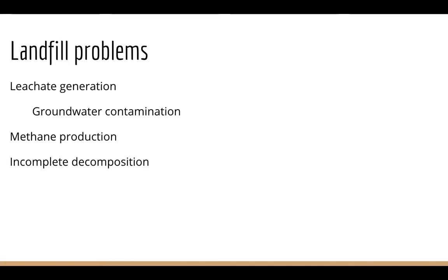So with this incomplete decomposition, you get really slow degradation of materials. More water will result in faster biodegrading, but more water also results in a greater amount of leachate. But actually in a landfill, you don't necessarily want decomposition, because if you have this mound of trash that's been capped off and sealed off, and now all of a sudden things are decomposing, those things will start to shrink in size, and then the landfill can actually collapse in on itself.